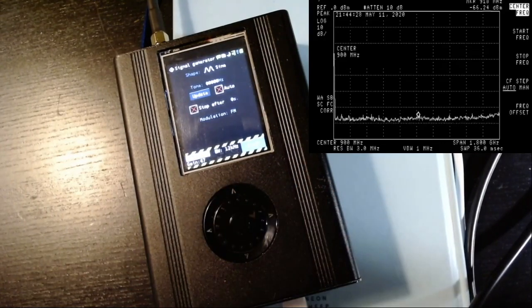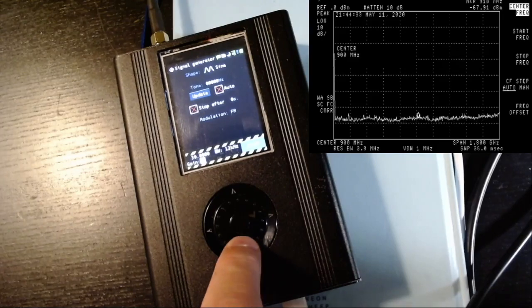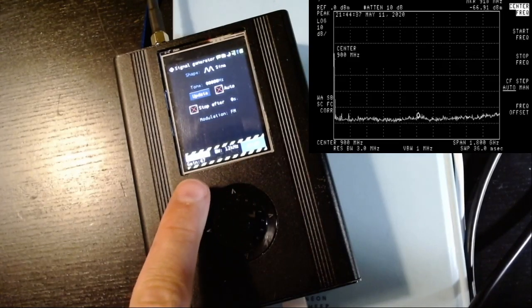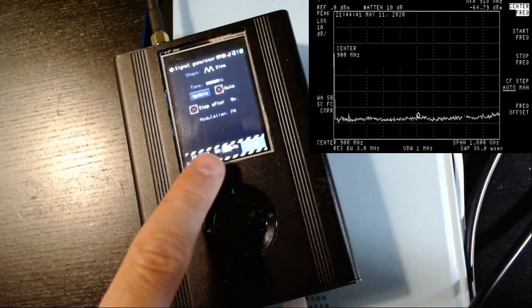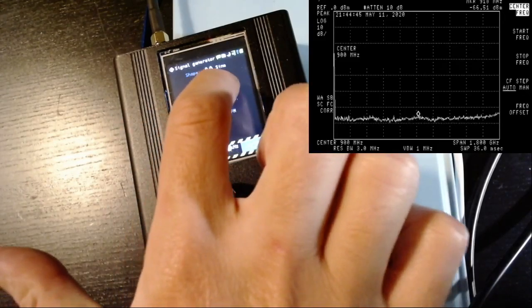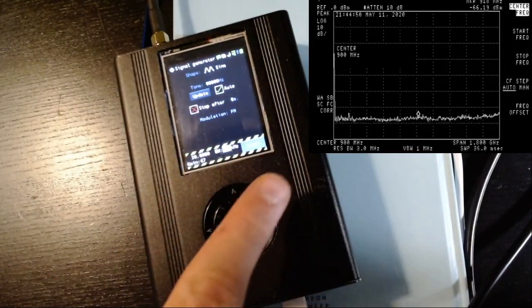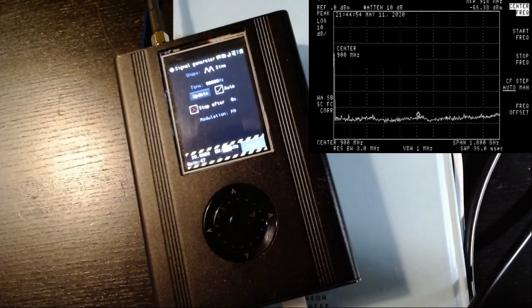At the moment we have 30 megahertz. Here we can set the level. At the moment it is set at 47, which is the maximum. The bandwidth is irrelevant since we are not modulating any tone. I'm going to click here auto, so the modifications that I make will be activated immediately on the fly by the signal generator, and so I'm ready to start now.